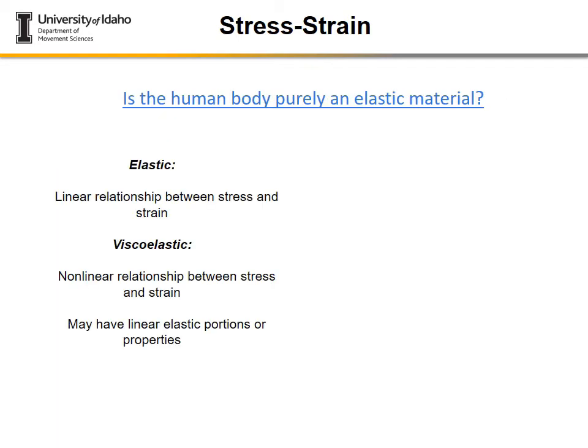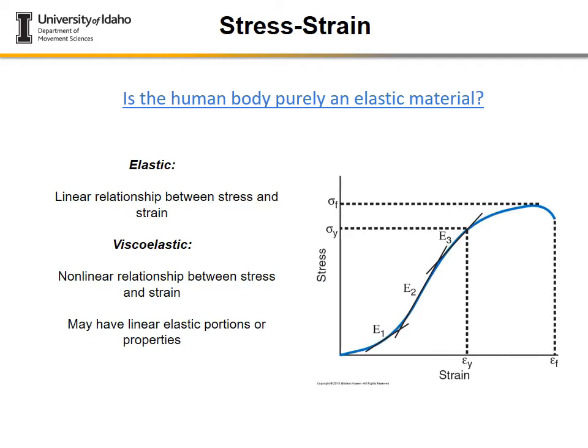So the relationship between the elastic and plastic regions is easily understood for elastic materials with a linear relationship during the elastic region. And that's like with the footwear and most of your material properties throughout the world. Now, I will tell you, when we do footwear testing, we do a series of impacts before we actually measure it, because we want to heat up the material a little bit, because materials do behave differently when they're warm versus cold. So we want to make sure that the material is at the proper temperature,